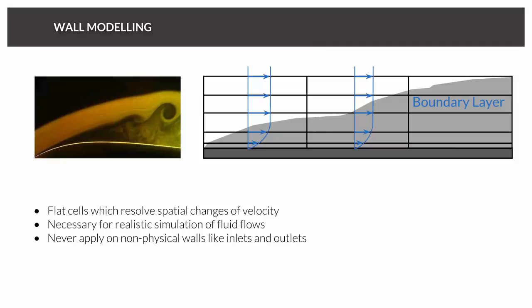And you maybe also remember that inside this boundary layer I have a very high gradient, because the fluid directly on the wall has a sticking condition, the no-slip condition, so the velocity itself is 0 meters per second in all three directions on the surface. At the outflow, it's like, let's say, 20-30 meters per second. In between we have a profile which is not linear, and it's actually looking like this. And this is our boundary layer profile.